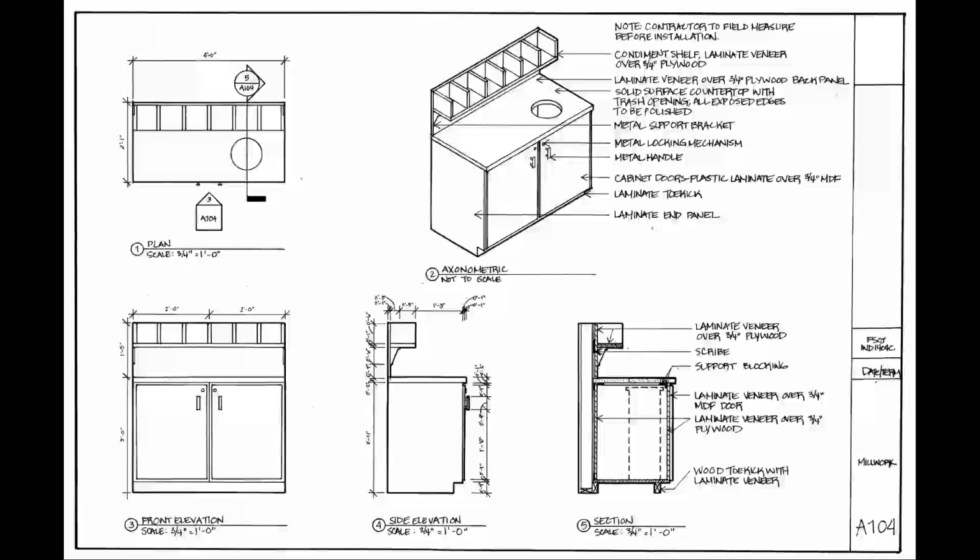You can see also that the drawing labels are drawn in the same way we saw in preceding videos, but just as a review, the number should be aligned with the left edge of the drawing, and the line itself should extend to the right edge of the drawing. You can see here we've got the drawing name and the scale.